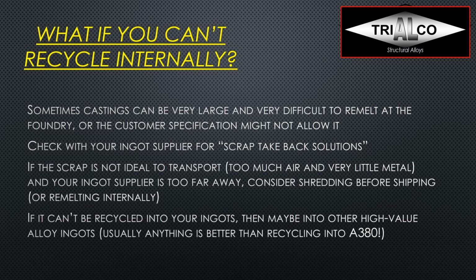If it can't be recycled into your ingots, then maybe into other high-value alloy ingots. And usually everything is better than recycling it back into A380, because some people don't like when I say that, but I just say it's the garbage alloy. If we can't recycle it in anything else that's of higher value, everything can go back into A380.